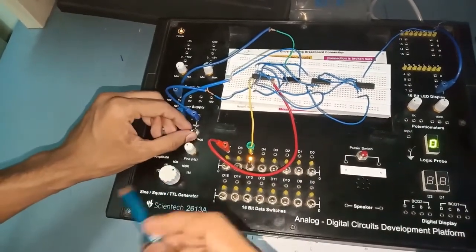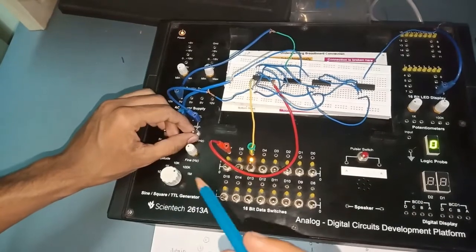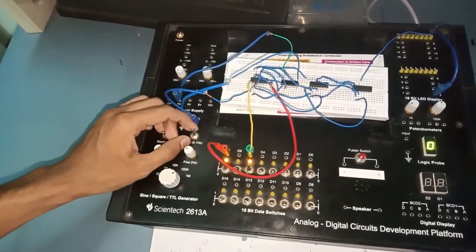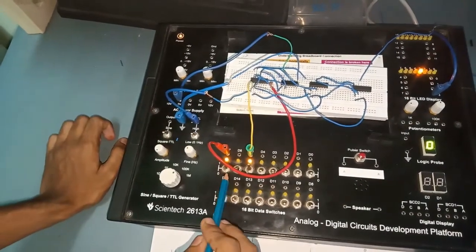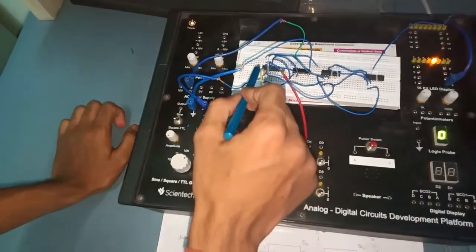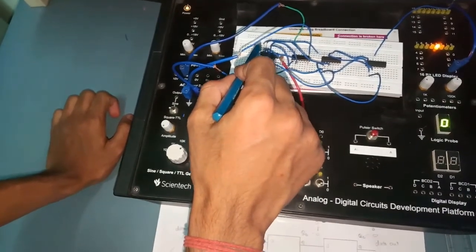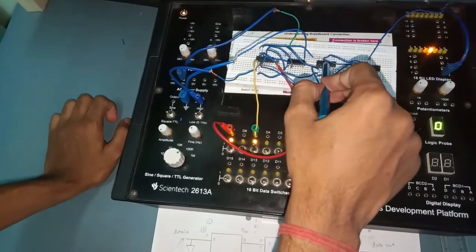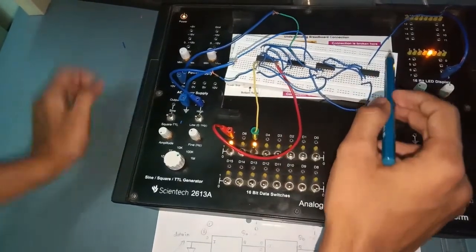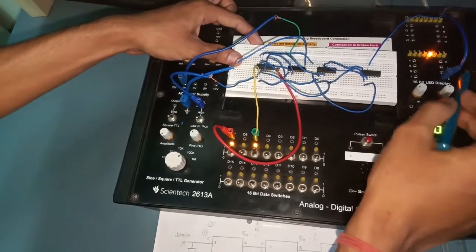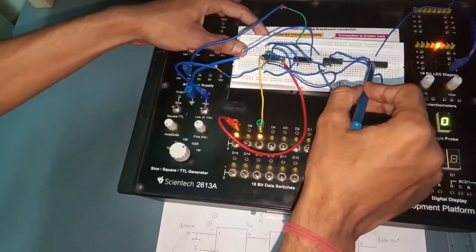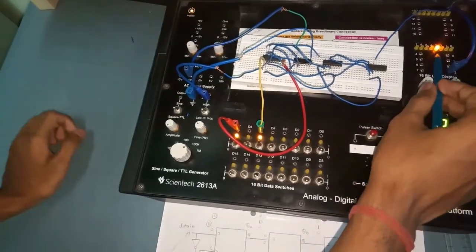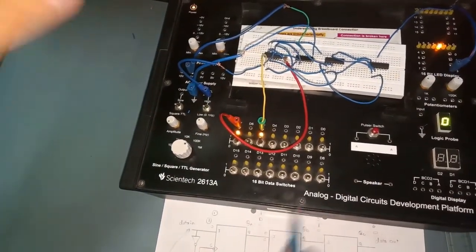Now we are going to give the third input, which is also 1. So at the next low clock, I am giving the input as 1. Now this 1 is stored in this flip-flop, and the previous 0 which was stored in this flip-flop is given to this one, and the 1 which was stored in this flip-flop is shifted to the next flip-flop. We have taken the output from pin number 12, so we can see the 1 stored in this flip-flop at the output. So the 1 which we had given at the very first low clock is displayed over here.